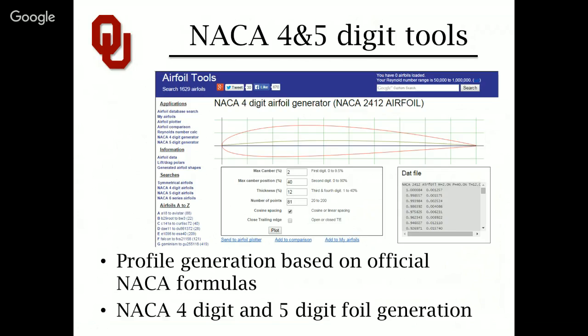Perhaps you've been convinced so far that it's a good thing to go check out. If you haven't, then you'll probably hear me talk about it a couple more times. But it can generate NACA 4-digit, 5-digit, and some higher order foils, both with reflex camber lines and without. Lots and lots of good shapes can be generated this way. And if they don't already have a pressure distribution for that NACA foil, you can always grab what's called the DAT file. You see it here in this region.